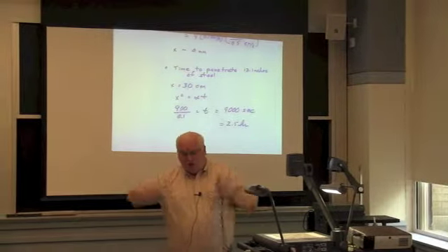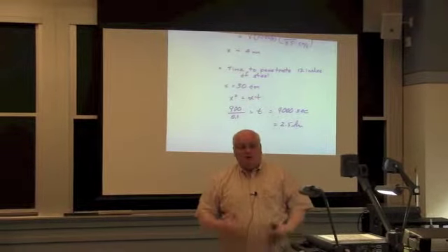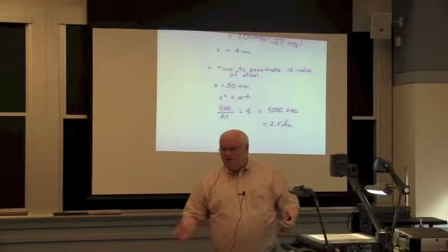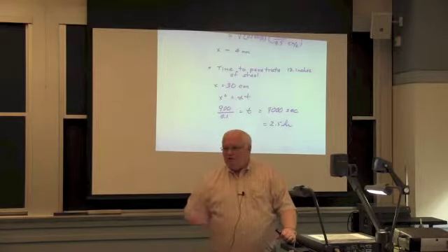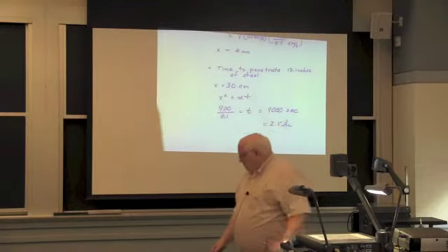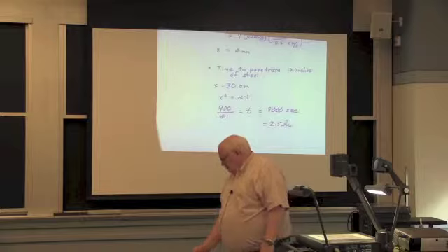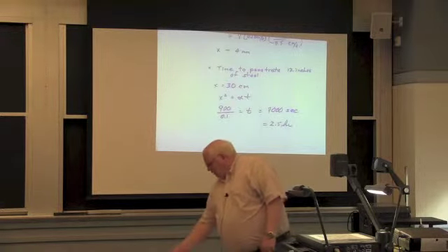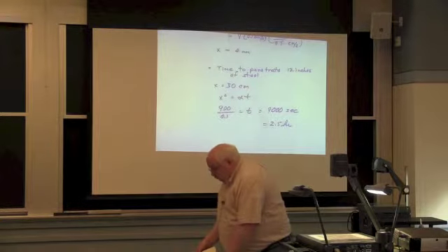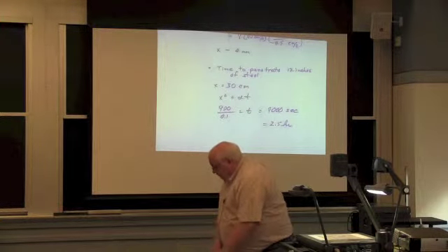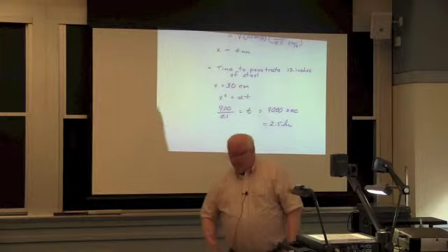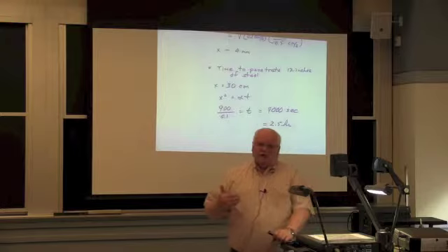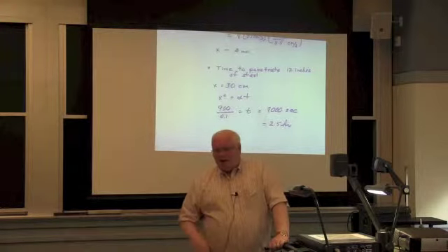So they put it on the press, and the first time they loaded it, because of the significant residual stresses, they did no stress relief. Wham, crack. At that point, they just scrapped the whole press. Used, it's only about a $5 million press, but it's destroyed, and to buy a new one is probably about $50 million. But anyway, there are a lot of problems with people not understanding heat flow and preheating and things like that.